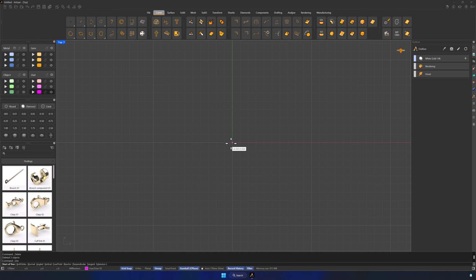Now, from the central point, draw a 10mm line to the right along the x-axis. Use 10 squares from the grid as a reference or type 10 in the command bar and click on the right side. Now, right-click to repeat the last command.